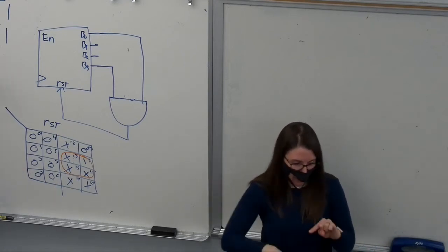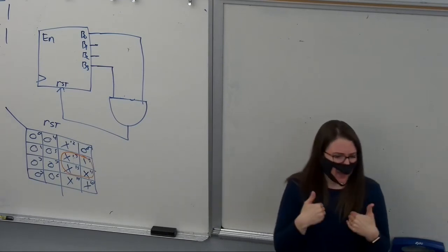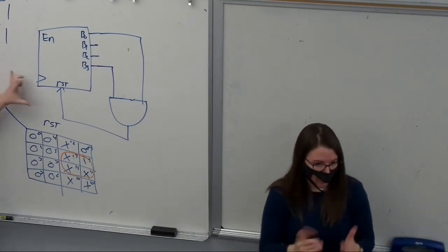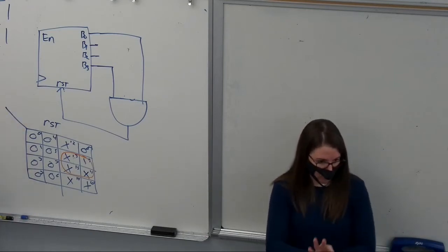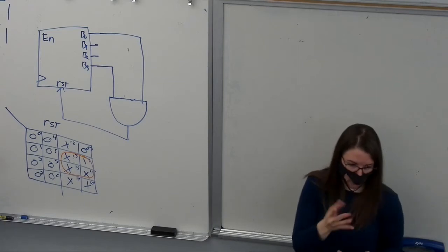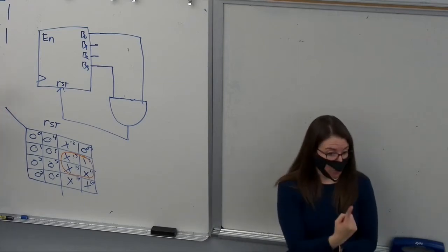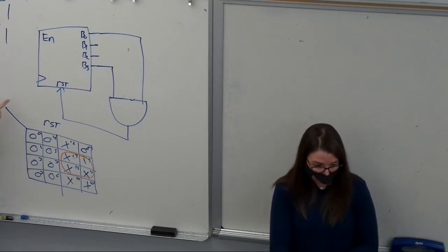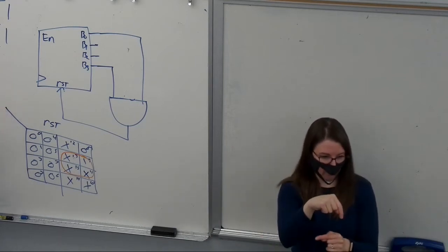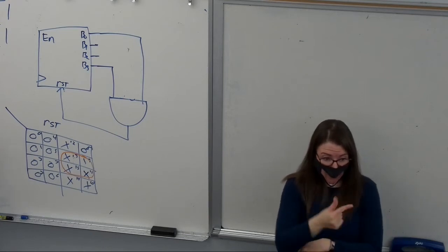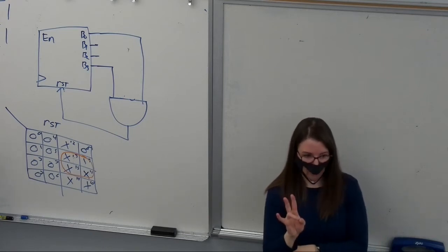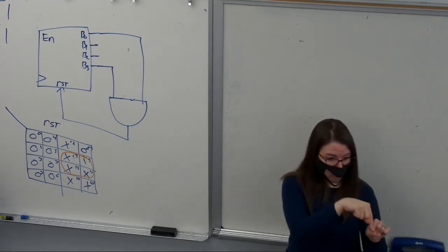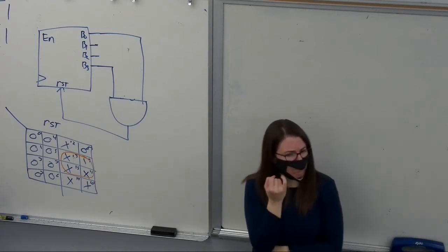Except for maybe like we do E for error, right? That was one of our examples. Okay, so now we have 1 BCD counter, right? It would go up, you go 0 to 9 and then reset back around. You've seen this, right? They have one of these on the FPGAs that we started touching in lab 7, where it just starts as a counter that goes from 0 to 9 and resets, right? But what if I wanted to count up from 0 to 19?